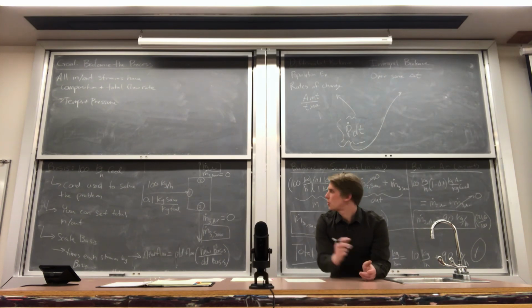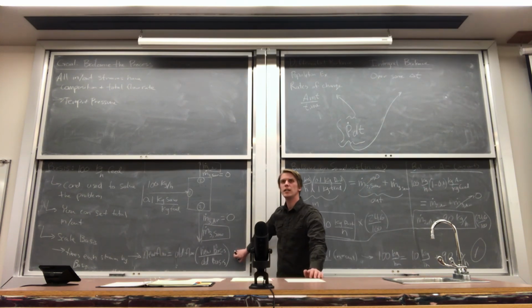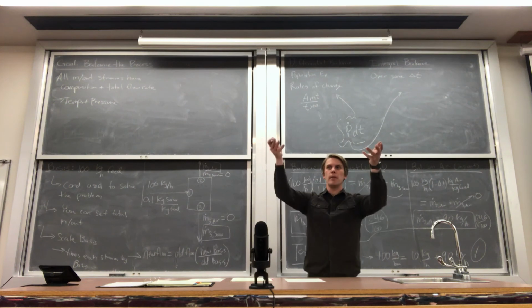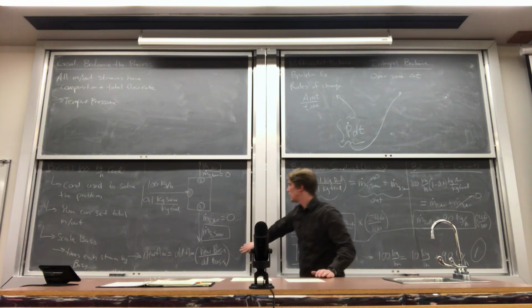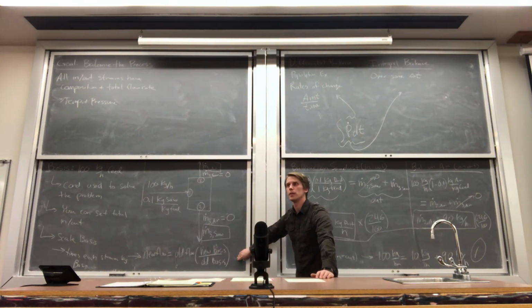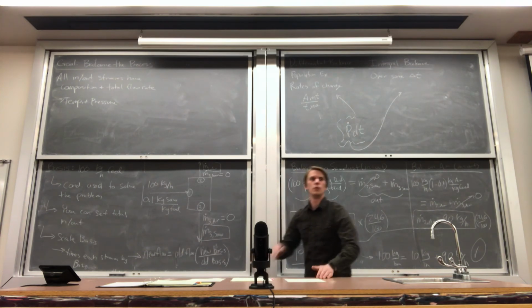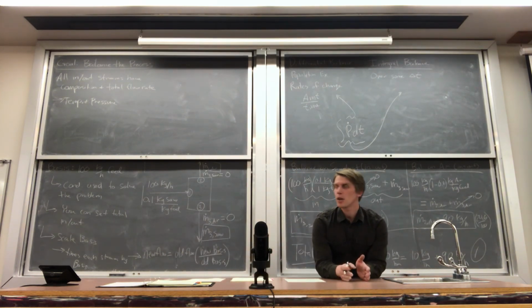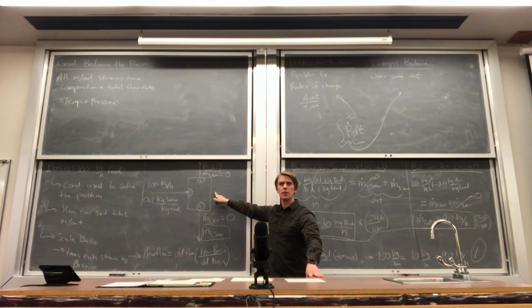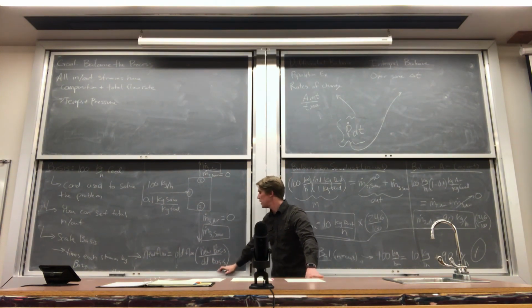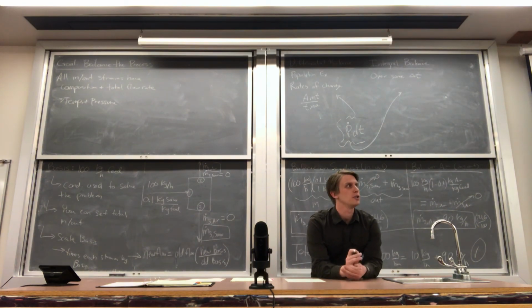So in general, solve the problems in an easy to use set of units. And then once you've balanced the entire process, you can scale every stream in and every stream out by the same amount, following this general equation here, right? You've chosen a basis that is easy to solve the problem, in this case here, 100 kilograms per hour, and then we scale it to whatever the real conditions are that the actual process goes through, and that's called choosing a basis and scaling a basis. Okay, any questions on this?